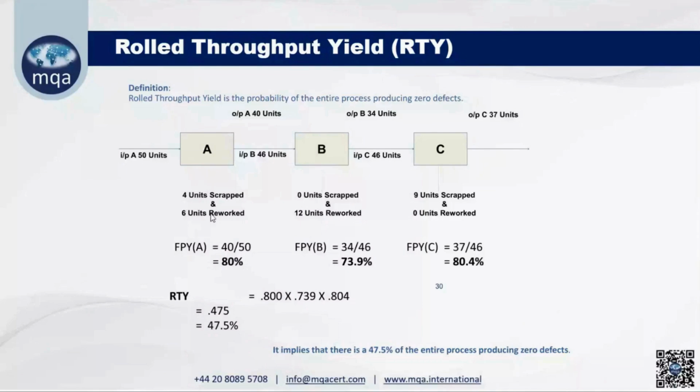For example, first pass yield: 6 units scrap, 4 units scrap, 6 rework, so total 10 units minus. Out of 50 units, input was 50, so out of 50, 40 by 50 is 80%. Again, what is yield? Yield is the good parts, good production.